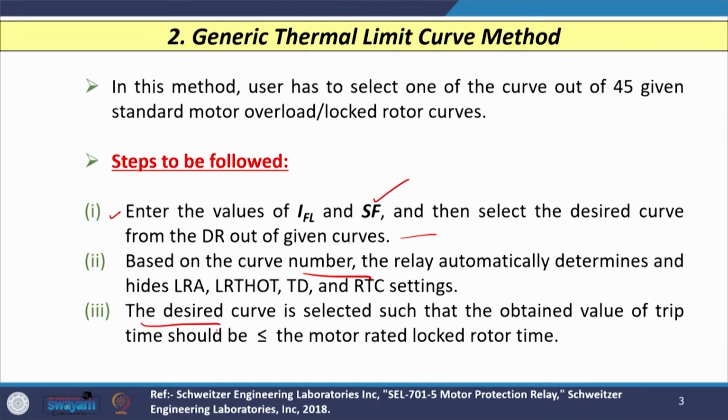Then the desired curve is selected in such a way that the obtained value of trip time should be less than or equal to the motor rated locked rotor time. So, this is a very important point we need to consider.